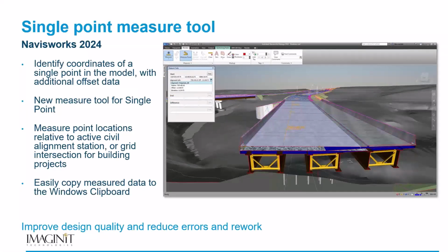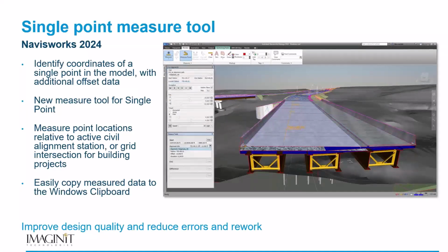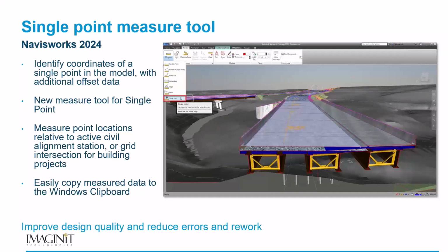As you're measuring, there's an option of giving a distance, but also doing a single point measure from within the Civil software here, and navigate through those cross sections as you start pulling the data that is readily available for you from the model that you're loading. It is alignment aware in this release and allows you to navigate from one alignment to the next really easily.